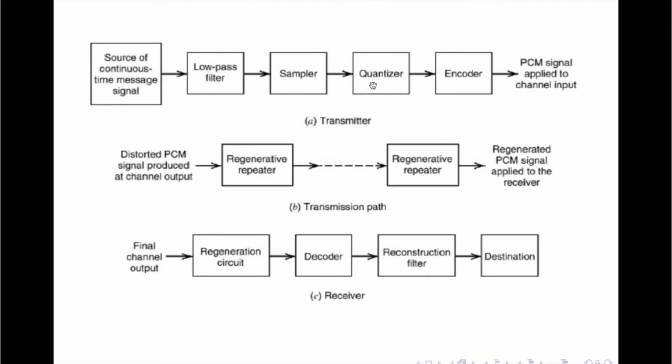The first one is that the peak-to-peak range of the input sample amplitudes is subdivided into a finite set of decision levels or decision thresholds. Secondly, the output is assigned a discrete value selected from a finite set of representation levels, also called reconstruction levels or quantization levels. In the case of a uniform quantizer, the separation between the decision thresholds and the separation between the representation levels of the quantizer will be a common value, and this value is called the step size.